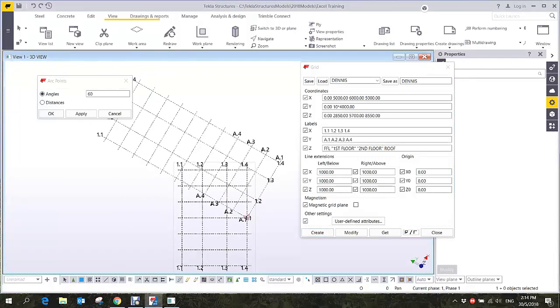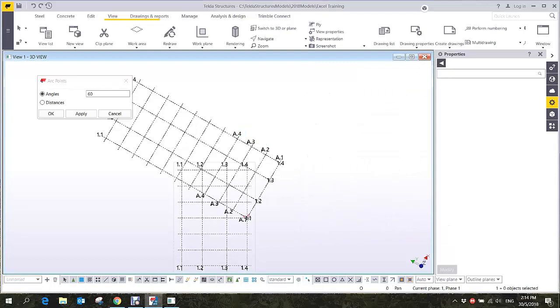So this is the other way around. Earlier, remember this morning how we create this diagonal one? Move, copy, and then rotate. This one, change the UCS and then create. Same output, different way of doing it. So it's your choice which one is much easier. Okay? All right. So now let's move on.